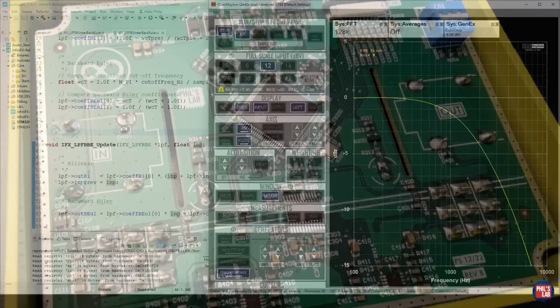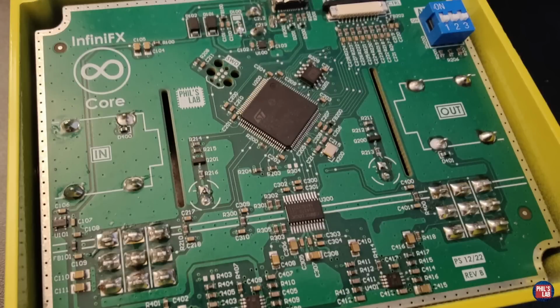The system we're running this on is a custom guitar digital effects processing unit, which consists of an STM32H7 microcontroller, various control interfaces via ADCs, controlled via switches and potentiometers. The STM32H7 also interfaces with an audio codec, which contains an audio ADC and an audio DAC, so I can take in guitar signal from my input, feed it through the codec, do some processing in the STM32H7 microcontroller, send it back out through the codec and the DAC and to the output stage.